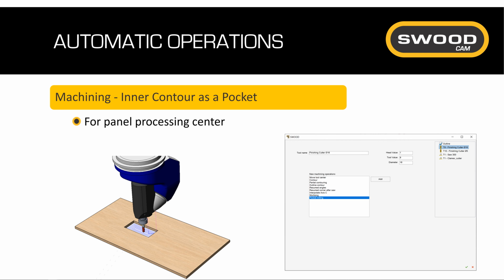Okay, so now let's continue with one other automatic operation that was added to this SWOOD 2021 release. As you can see here, you will now be able to machine your inner contour as a pocket. Basically that means that the tool will start at the center of the inner contour and then go to the outside. The main reason why we created that is for panel processing centers, because for this kind of machine, you can't have waste material. That's true for horizontal and vertical machines, for instance the BHX from Homag, the Brema from BSA, or the CX from SCM.